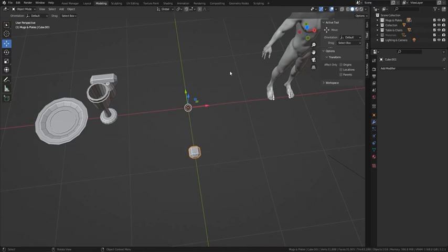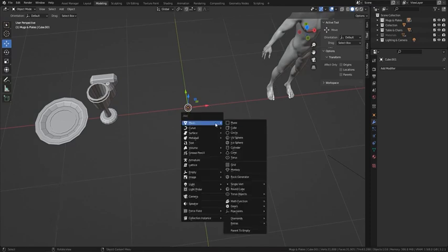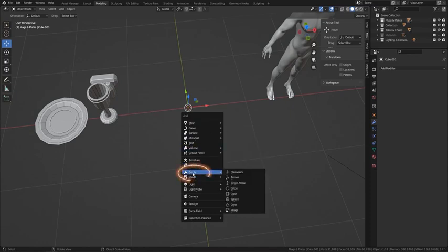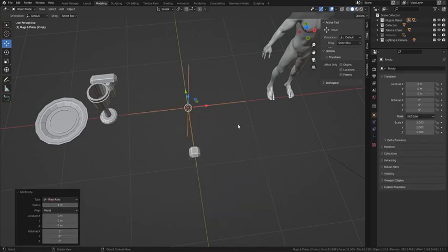The easiest way I've found to do it is simply to bring in an empty. So you can see here it says empty, bring in a plane axis. Now an empty is something you can use to do animations, or to do things like what we're doing here, using it to create arrays and things like that. An empty is basically a piece of mesh that will never be shown in the render, so you'll never see this actual piece of mesh. That's why it's called an empty. It's similar to when we're deleting vertices instead of faces, apart from it's actually used for a purpose.